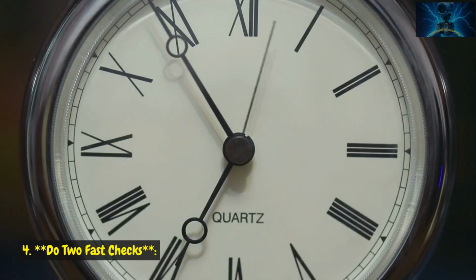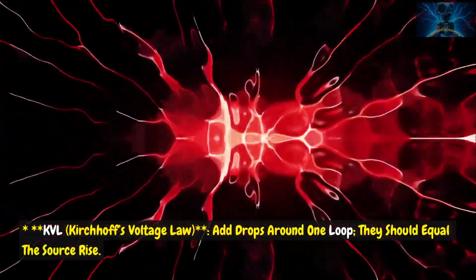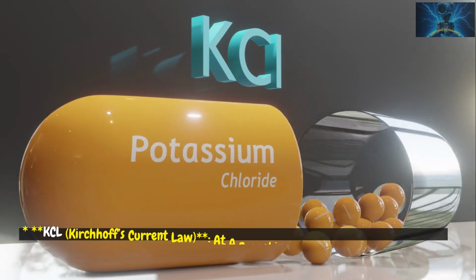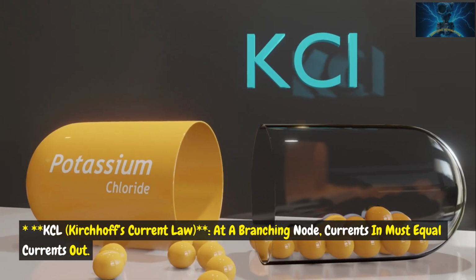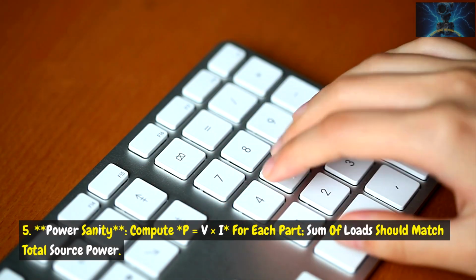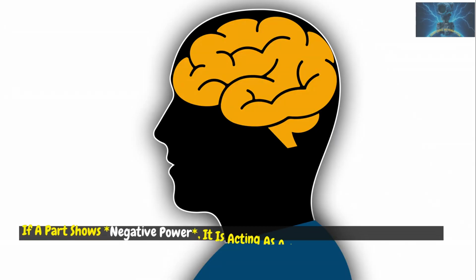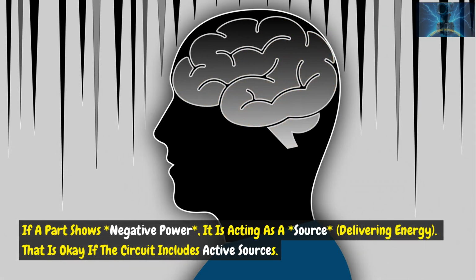4. Do 2 fast checks. KVL, Kirchhoff's voltage law: add drops around one loop. They should equal the source rise. KCL, Kirchhoff's current law: at a branching node, currents in must equal currents out. 5. Power sanity. Compute P equals V times I for each part. The sum of loads should match total source power. If a part shows negative power, it is acting as a source, delivering energy. That is okay if the circuit includes active sources.